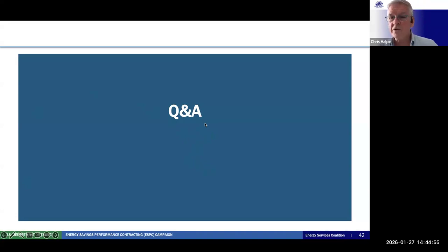And first step in energy efficiency is always measurement and benchmarking. Yes, that makes sense. You want to make sure you know how much you're spending and where before you get into a project like this. That's right. The first part of measurement and verification is baselining, right? You baseline not only your energy costs and the usage, but you baseline how you're operating and maintaining your buildings. Because without those two, you're not going to be able to calculate and measure the savings that you have.